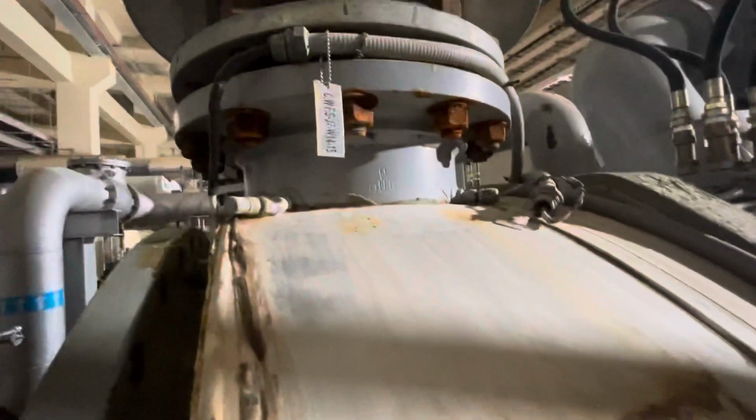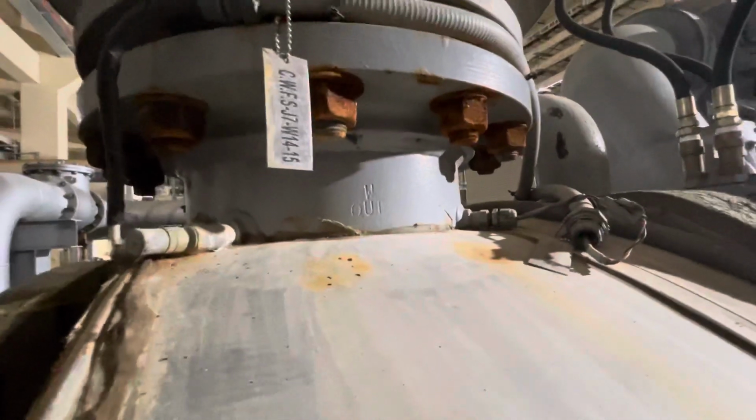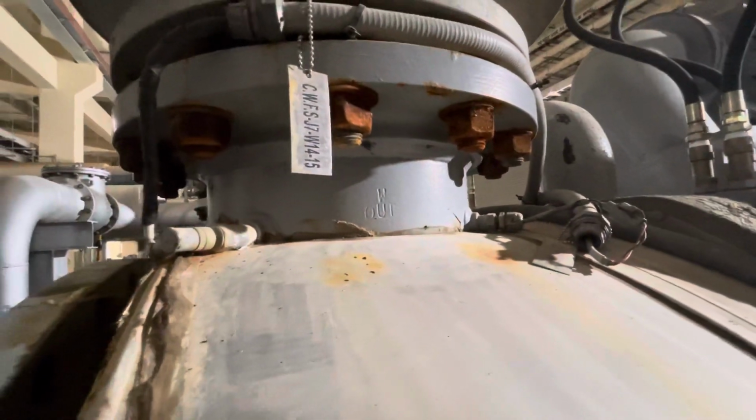The same way as the condenser, here are also temperature and flow sensors. You can see here, temperature and flow sensor. In case there is no flow, it will trip the chiller, because if there is no flow, it will damage the tube. So to protect the tube, there is a flow sensor here.